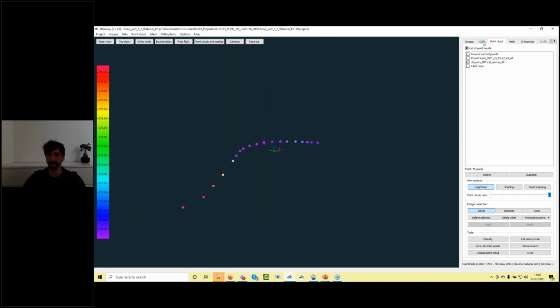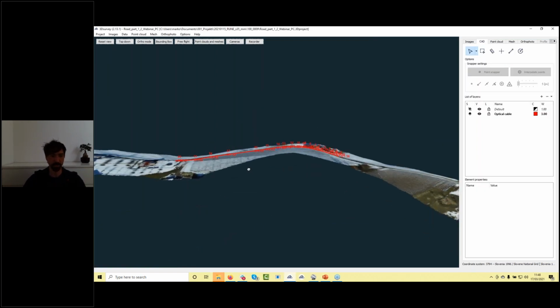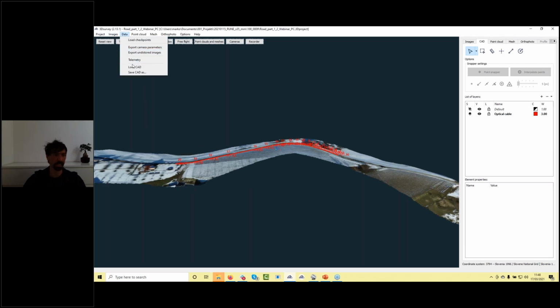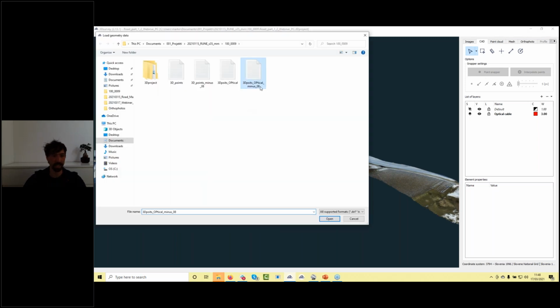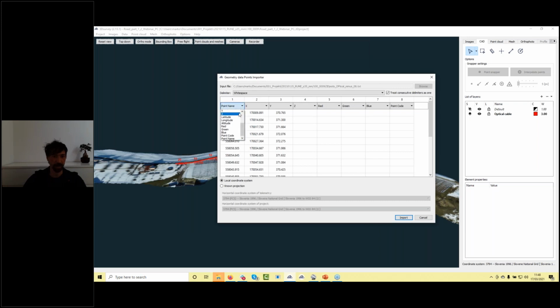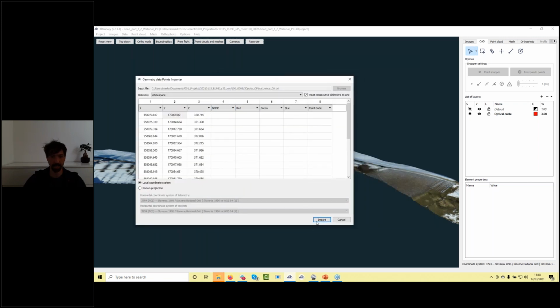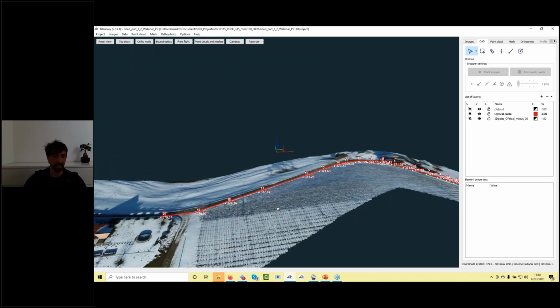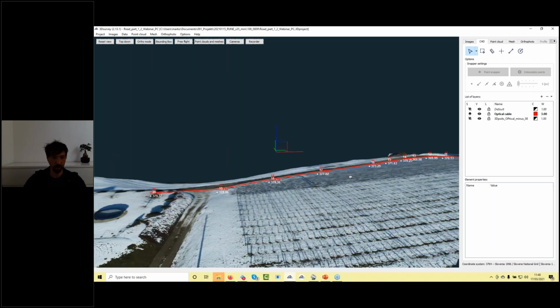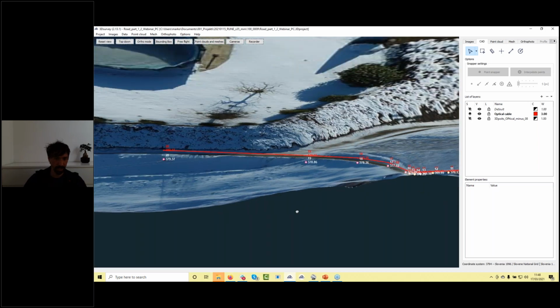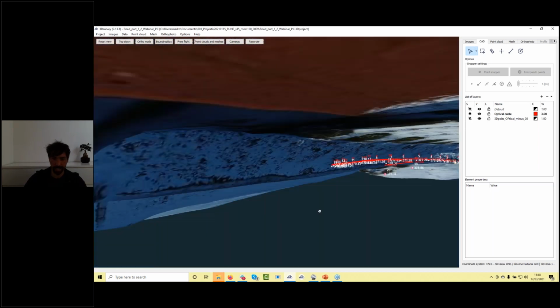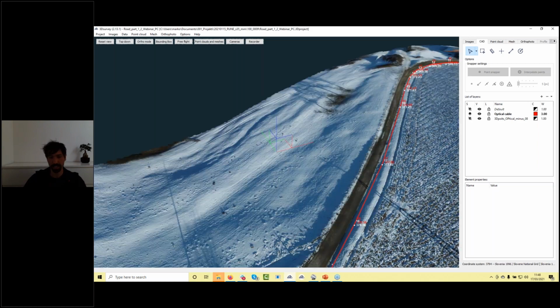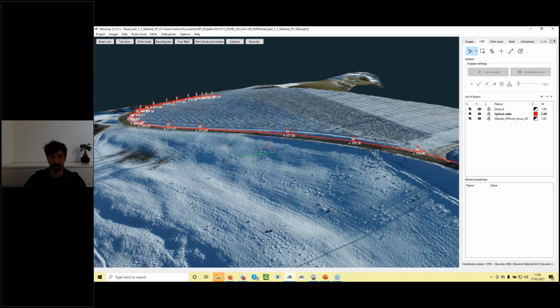That's it. And now if I go back to my CAD tab to import those points inside, just data, load CAD, my manipulated points, again set the X, Y, and Z value correctly, and import them again. And here we can see them in white color, my 3D points with the lowered height. Okay, so if you need to design them like so, you can do it immediately.